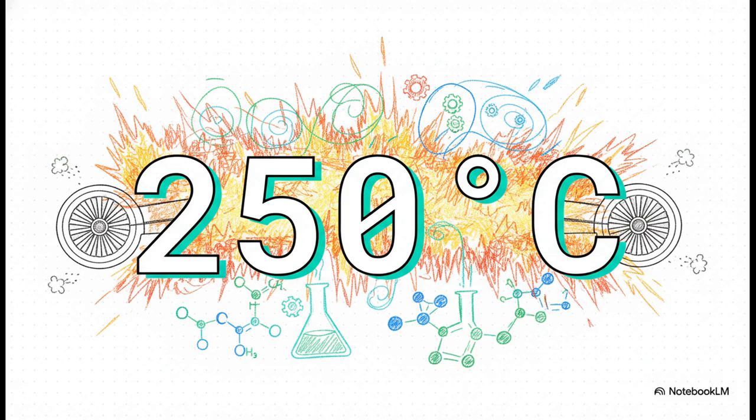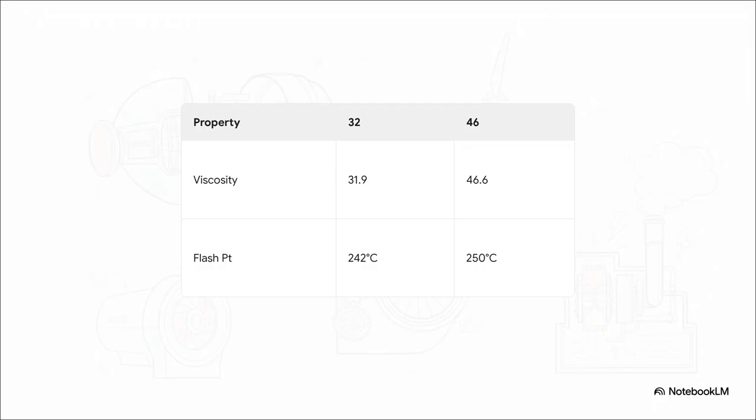Case in point, industrial turbine oils need a massive flash point of 250 degrees Celsius just to prevent a catastrophic failure. Seriously, if that oil degrades or ignites, the entire multi-million-dollar system literally destroys itself in a matter of seconds. And this is exactly where specialized chemistry steps up to the plate. Take PTT Lubricants Turbine M, for example. It's an incredibly advanced oil designed specifically for water, steam, and gas turbines. It completely solves these intense thermal and friction problems using super high-quality hydro-treated base stocks.